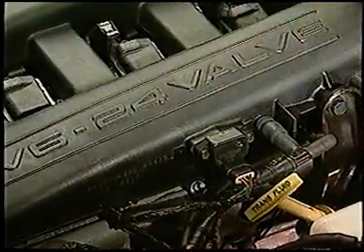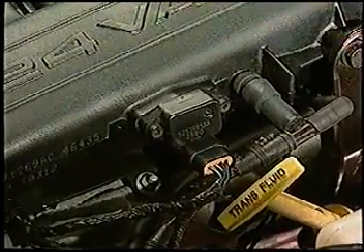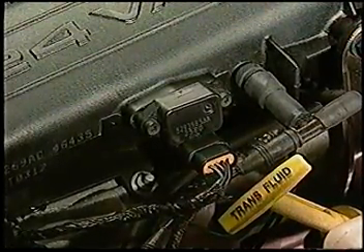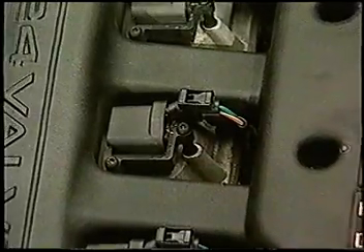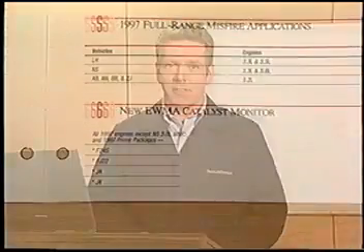In other words, the PCM checks input signals to verify they make sense when compared to other input signals. And it checks output signals to be sure they have the anticipated effect. Finally, beginning in the 2002 model year, a positive crankcase ventilation, or PCV, system monitor will begin its phase-in plan in states requiring California emissions. It will be used to monitor the integrity of the crankcase ventilation system.